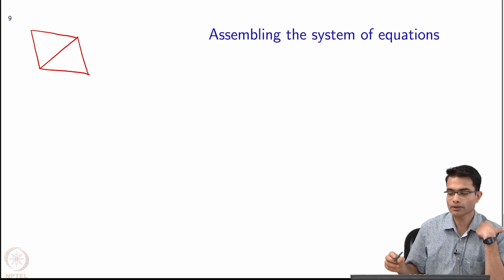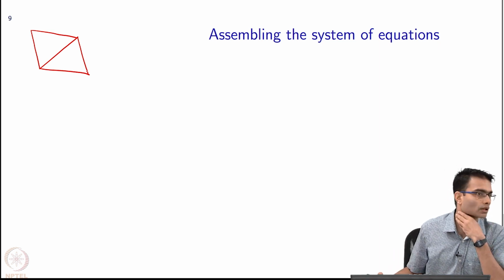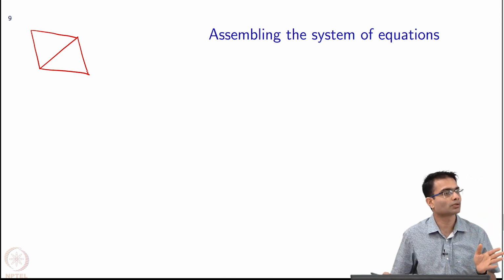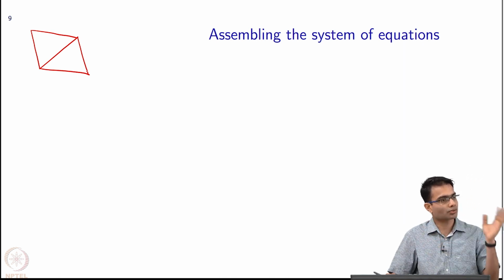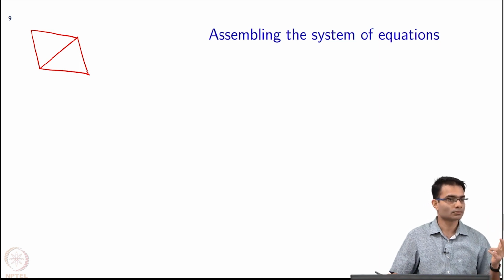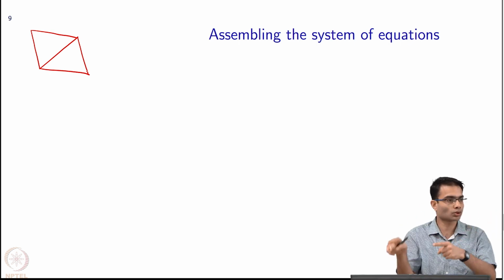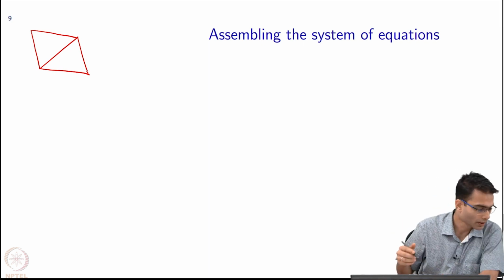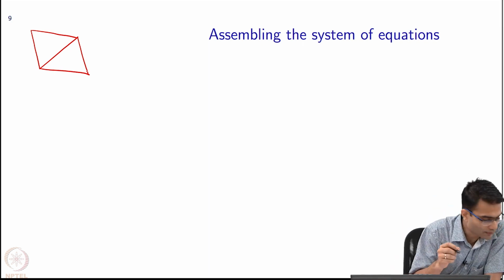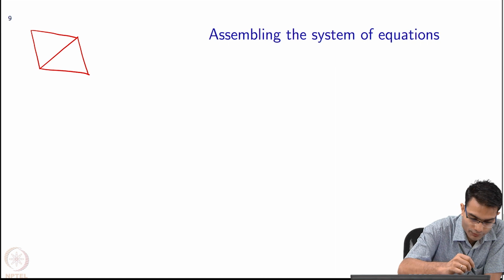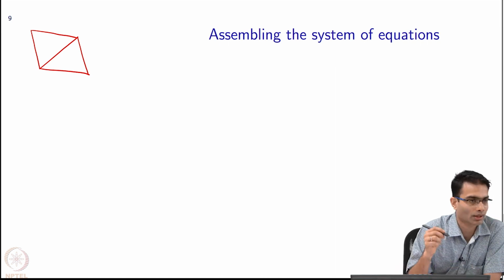Okay. Now, one very important thing to keep in mind in FEM in general is the mapping between global nodes to local nodes to global nodes. Okay. Not just nodes, now we are talking about edges, right. This is an edge based FEM. So, we also have to keep a table which allows me to go from a local edge to a global edge numbering. Okay. So, each of these I will use a different color for, let us use the color green